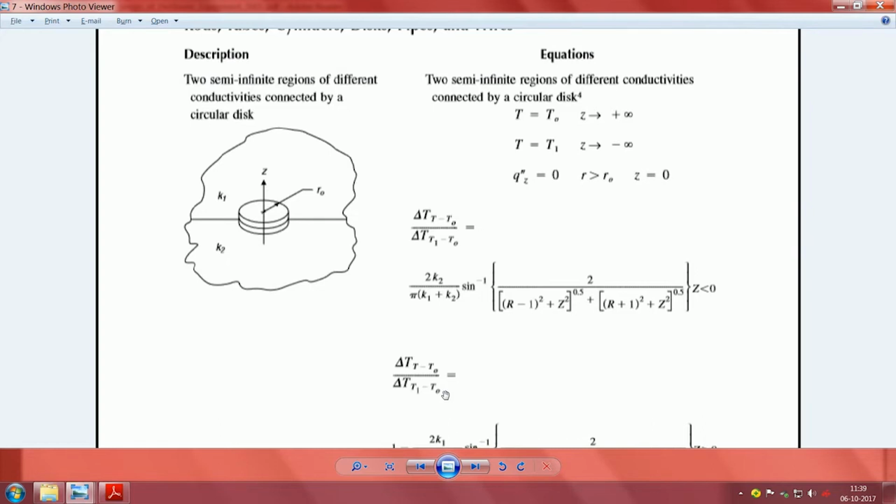If you remember, in the first introductory lecture I showed you the Peltier, a small heater cum cooler, what we are doing there. There you will see Peltier is usually a 30 mm by 30 mm square. The Peltier device is only a 30 mm square, and that is attached to a plate, and one side it is cold and one side it is hot, relative of course, higher temperature and lower temperature, and you reverse the current. There things like this are very, very useful.